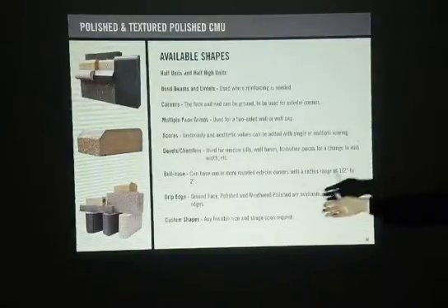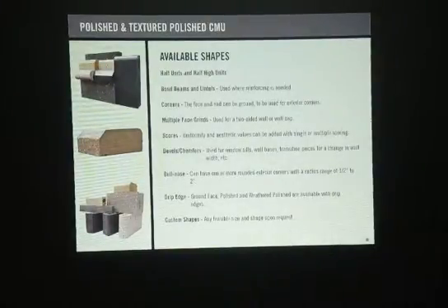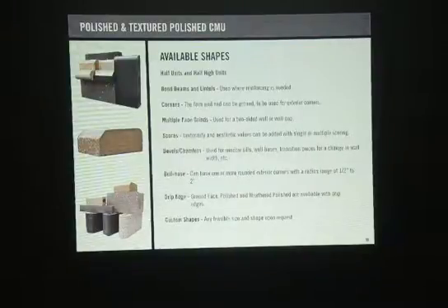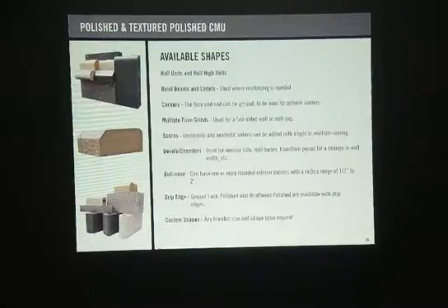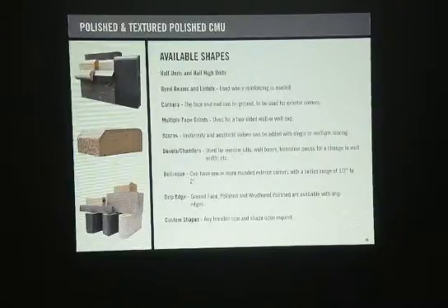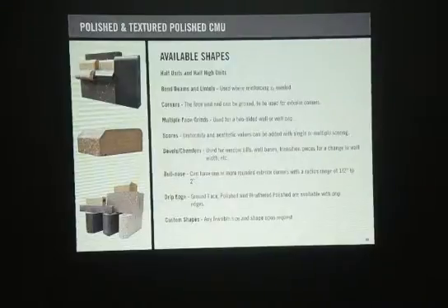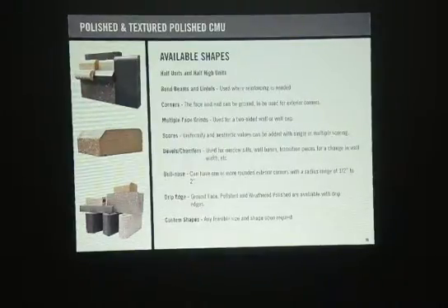And as you can see here, there's a lot of available shapes, okay? Sometimes, because you're working with corners, doors or windows, you cannot put a whole 8 by 8 by 16 block on the surface. So you get hacks, or you have them cut a certain special way so that the block fits into what is needed, and it looks like it all belongs, because it does, and we can make those special blocks at the factory, okay?